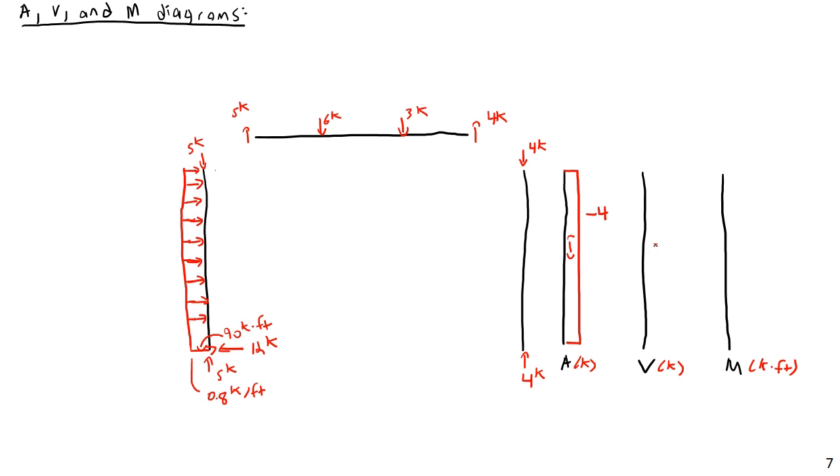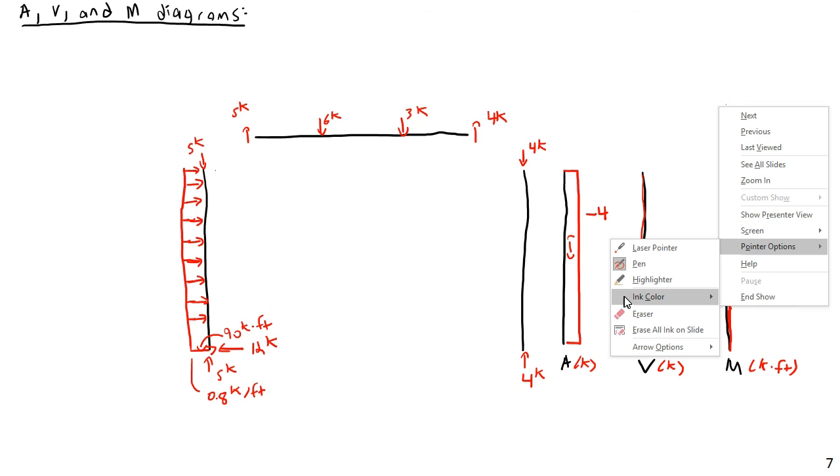Then what about the shear on this thing? There is absolutely no shear on this, and that is because there is no transverse force on this column. Again, transverse force refers to force perpendicular to the member's axis. There is no shear, and there is also no moment in turn because there are no end moments. There are no couples on the thing. There's no transverse loading, so therefore the moment is also equal to 0. No moment. Okay, then on the beam, let's go to the beam.